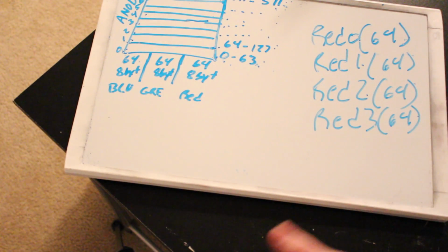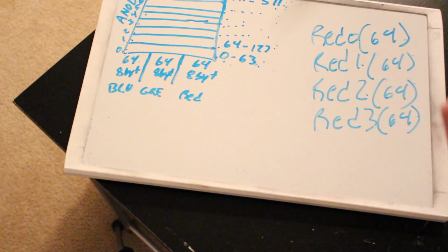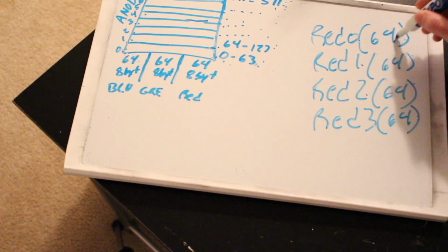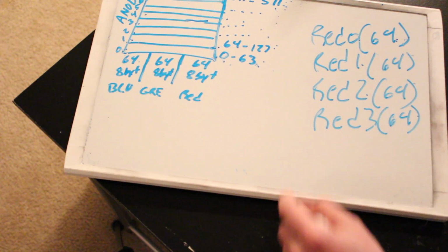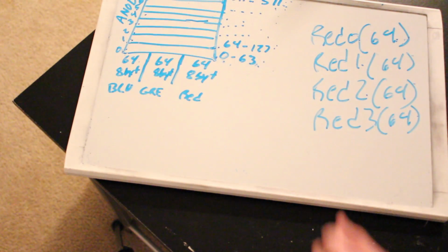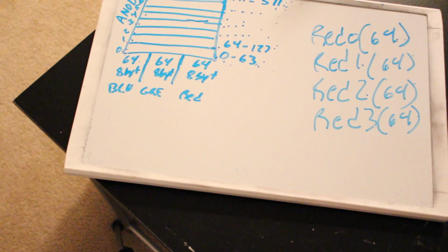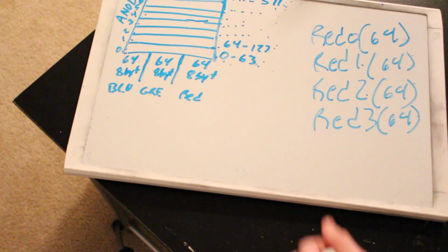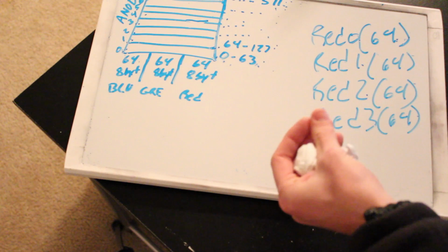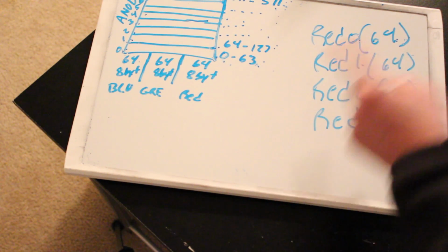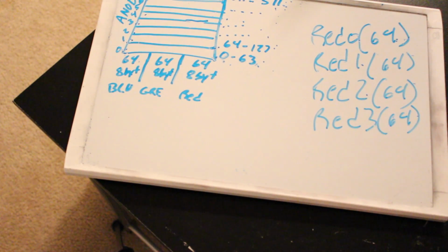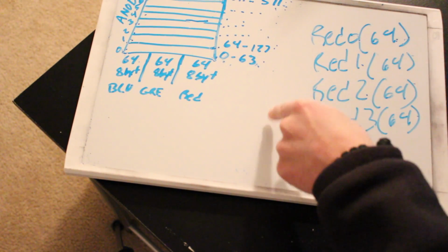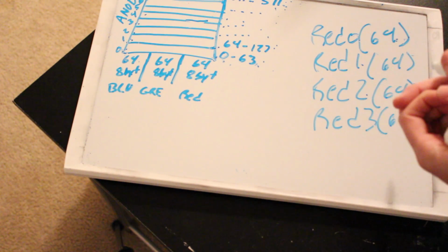Then it would go through again, and then this one would then be activated, since it's 2, and it goes through. So basically when we enter into the LED subroutine, what we're interested in finding out is which one of these bytes corresponds to whichever LED in the cube you're controlling. So that's what that first calculation is. The second calculation is then trying to find out which bit in the byte we're trying to write to. Based on the brightness, then now we know which LED we're trying to control.